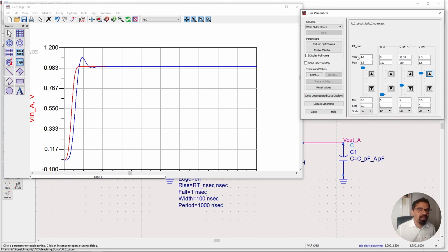So if you're just doing a traditional RLC circuit, you really wouldn't care too much about the rise time, because we could have a slower rise time for most circuits. When it comes to signal integrity, we're looking at high-speed signals. These things can switch at a very high speed, so the rise time becomes a very important parameter that we want to focus on, and then design our circuit so that we can minimize this ringing effect. And that's really what I wanted to show you as to why an RLC network or system is so important, because this can